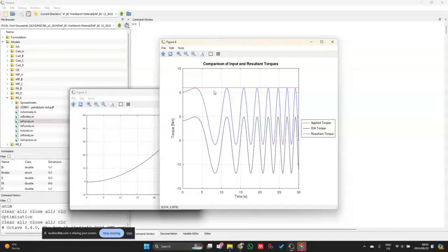If I specify anything smaller than that, then it means that I'm going to sit over here and the resultant torque is most likely going to be larger than that. And what that will cause is that the pendulum is not going to actually rotate all the way counterclockwise. Instead, you're going to have this very localized oscillatory motion where the torque basically picks up the pendulum, but then it's not enough to overcome the effects of gravity, and then it's going to fall back. And it's going to be this picking up and falling back oscillatory motion that you're going to see the entire time.